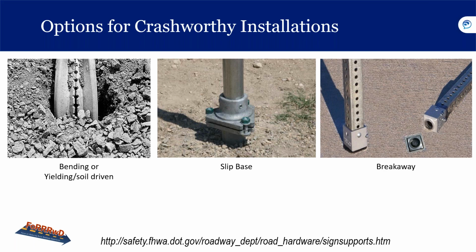No more than 3 posts in a 7-foot circle of 3 pounds or less, and they must be breakaway. Direct driven or field splices only 2 foot in a 7-foot span. Direct driven is acceptable given proper depth, soil type, and structural steel properties. Then we have the slip base in the middle for lightweight structural steel, number 3 or less, shown, and then our medium weight, which is 3 to 6 pounds per foot.